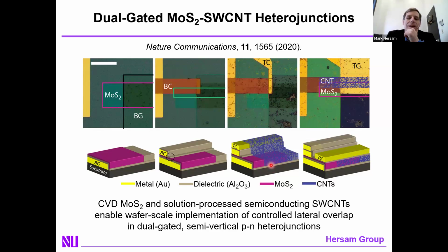The difference, though, is that this PN junction diode is made out of atomically thin materials, which means that the thickness of the device is thinner than the screening length of electric fields, which implies that this is a highly gateable PN junction, one where you can electrostatically modulate the carrier concentration just by applying voltages to the bottom and or top gate. Moreover, because it's mixed dimensional, the degree of screening is qualitatively different. It's much lower on the 1D side than the 2D side, and that asymmetry in screening gives you further tunability over the nonlinear current voltage characteristics.